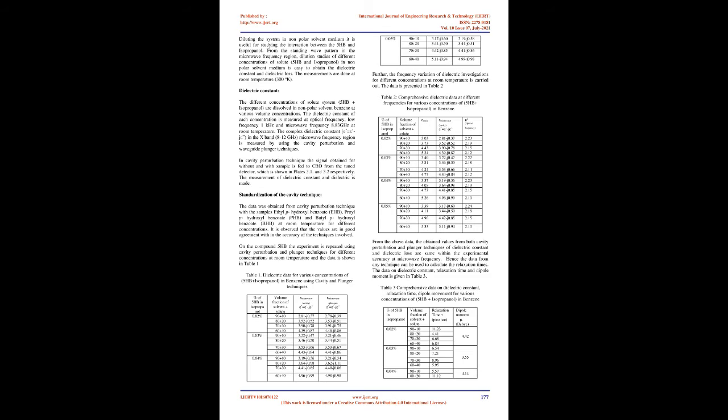The dielectric studies are carried out using LCR bridge for static dielectric constant, and the microwave bench adopting the plunger technique and the cavity perturbation technique method, in X-band. The resonant frequencies correspond to the empty cavity, the cavity with empty holder alone, and lastly the cavity containing holder with the sample. The dielectric constant is obtained through the equation.